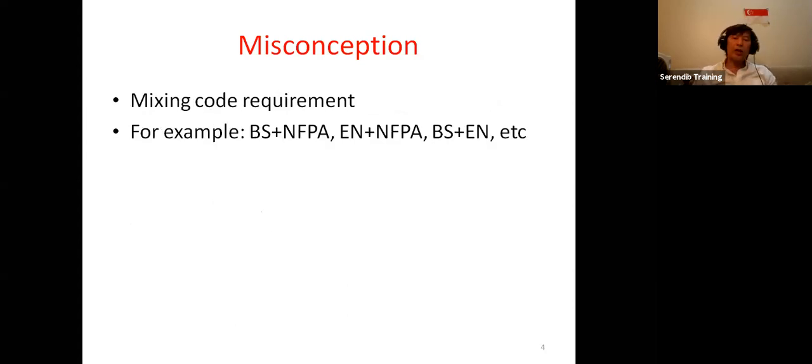The other misconception about cause and effect is the mixing of standards and codes. Very often, from my experience, I came across the habit of picking and choosing requirements from various standards of origin. For example, taking from British standards and a bit from NFPA, and trying to mix them and come out with whatever makes sense to them. This should not be practiced, because when you start to take requirements out of context, you may lose out on other cross-referencing that has an effect on the requirement that you have taken out to mix with another requirement.